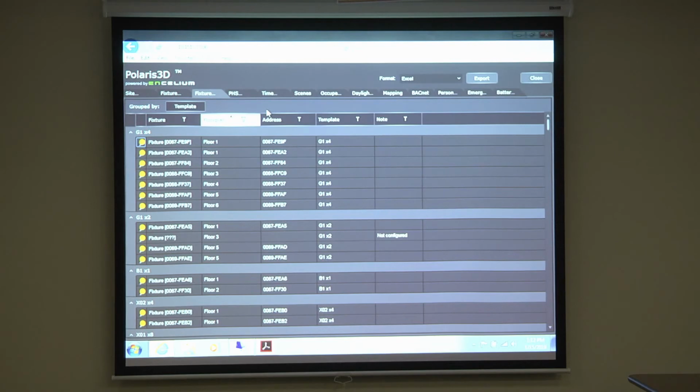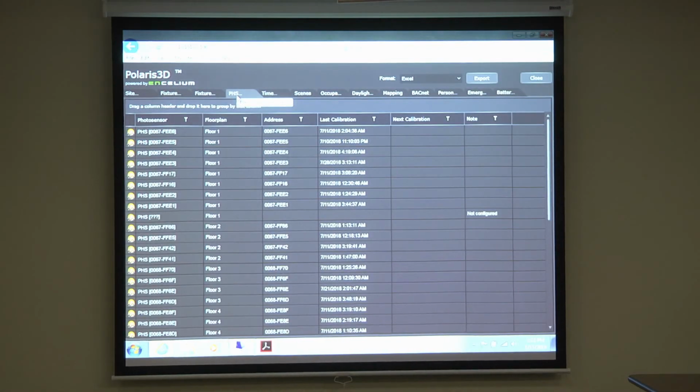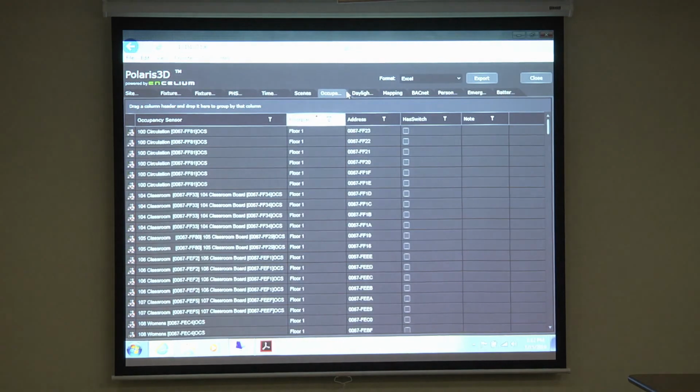Exactly. Okay, that's what's happening on that channel. I mean, granted, I think on all of them I've got at least 2 channels on each ECU, if not 3, as spares. But let's say it's all the way at the other end of the building and I have to run to map a new channel. I can't map a new channel off of another channel down the line; I actually have to come from the ECU.